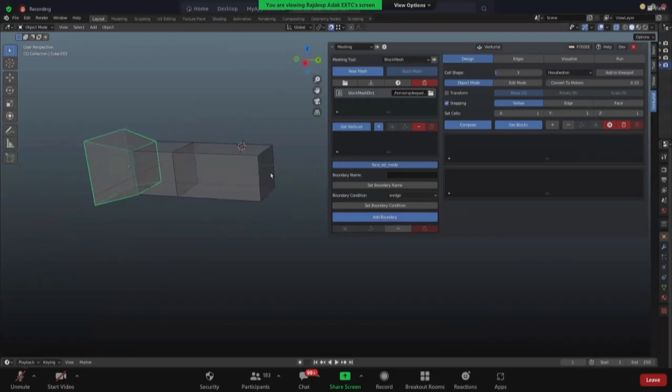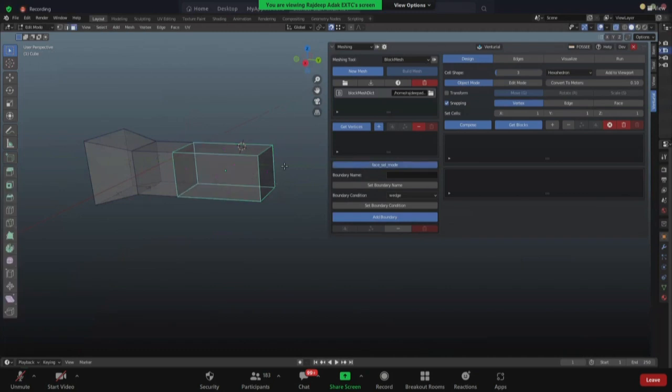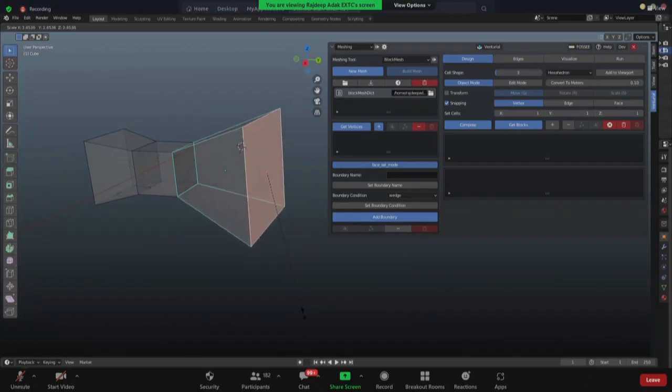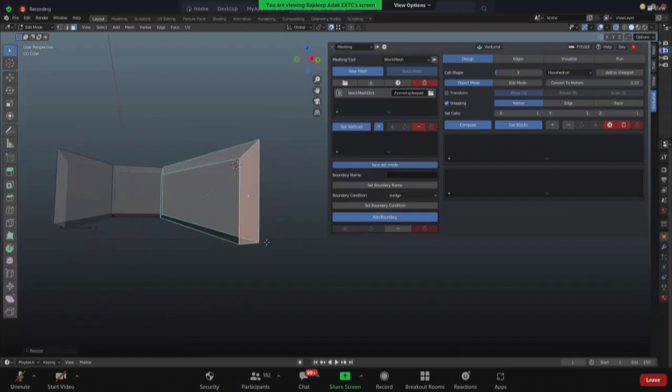Then you go to this block, okay. I have to scale this block up as well. I'm going to press the face select mode button again for this block. So this brings me to the face select mode for this block. Click on this face and then press the S button. That allows us to expand it as per our requirement, okay. So I'm just going to expand it a little bit. Just about this much should be fine, I think. So this is the kind of geometry that I was looking forward to, okay.